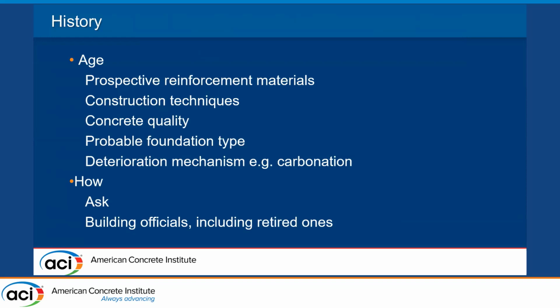And you look at deterioration mechanisms, carbonation, that's really important for determining the pH of the existing concrete. If the pH gets down to around 9 or so, your reinforcement is going to corrode a lot, which Fred can tell you a lot about. But that means, where does the inch and a half come from? A lot is at fire, but over about 50 years, that 1.5 inches will carbonate, your pH will reduce, and you can expect a lot of corrosion of reinforcement at that stage. So age becomes a really important idea.